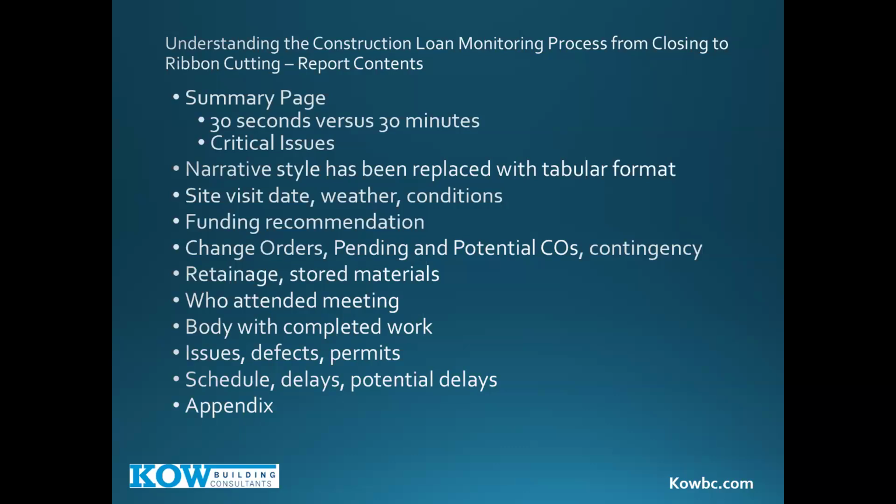Typically in areas that have harder weather, like the Northeast or the Northwest, etc., basically the northern part of our country, you really have 3 considerations which are very different during the winter. Very different. You have temperature, you have moisture, and you have wind. And they affect you differently. Temperature is going to affect things that are water-based, like concrete, caulking, painting, etc. Your precipitation, that's going to affect when you're able to install things like a roof. And then wind is going to affect things like siding, bulkhead work, scaffolding. So they're very different, but they're all very impactful to construction projects.